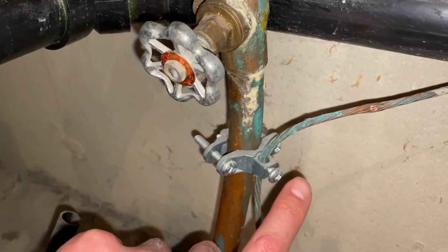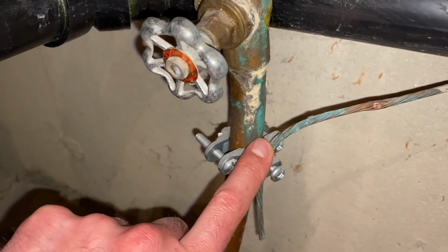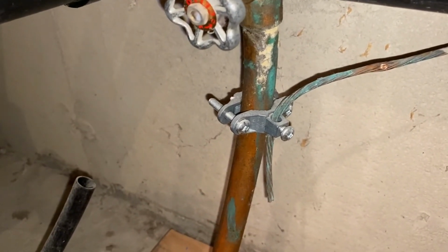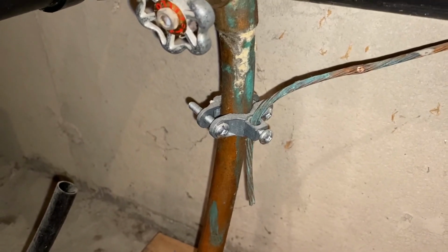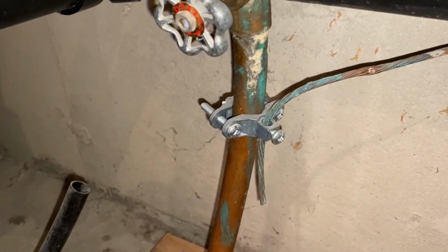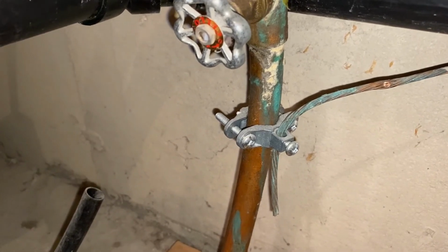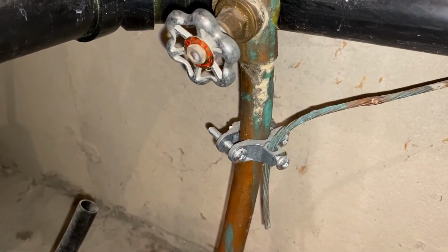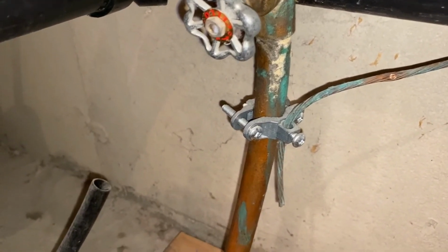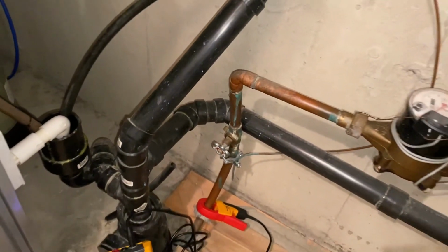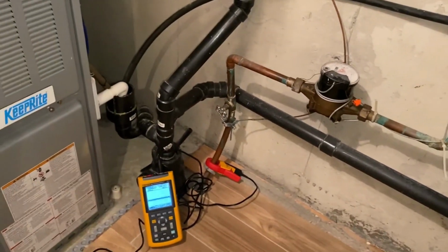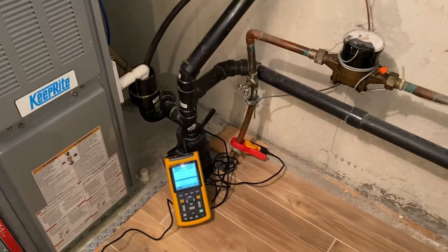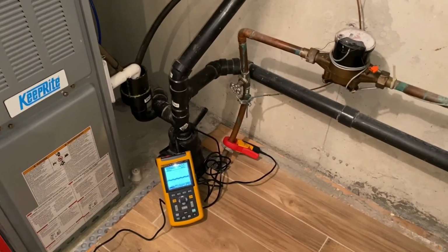And anytime we use a screw terminal type of connection like this, we're always adding some type of resistive quality into the conductive path. That's just the nature of using a terminal like this. They never give you a perfect zero resistance connection. It's just not possible. And in the electrical engineering world that I come from, we always used to say that the least amount of connections in a system, the better. And this is a perfect example of that.